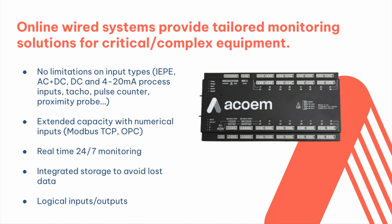The main reasons being there's no limitations for input types. So a wireless system has two main vibration types, the MEMS and piezoelectric sensors, and then they can take surface temperatures. Whereas a wired system can take in all different types of process data: accelerometer inputs, DC inputs, tach, pulses, speed, proximity probes, you name it, it can take that data in. So we can use all that data to get a better picture of the machine health.